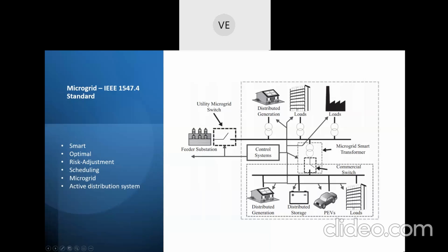So now the framework is that any scheduling process should be planned prior to the actual time horizon in which the actual transaction happens. Actual transaction in the sense, it can be the dispatch of distributed generators, then the dispatch or the charging of distributed storage. So here the output power can be positive or negative for distributed storage. Similarly for plug-in EVs also the output can be negative or positive power. I'm mentioning active power now.